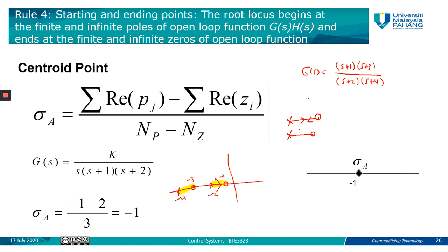So if you do not have an equal number of poles and zeros, that means I may have (s plus 2) over (s plus 3)(s plus 4). So I only have 1 zero and I have 2 poles. So how will the poles be aimed? That means they have to start from -3 and end at the one zero, and start at -4 and end where? I do not have another zero here. To which place should this pole go? That means we have finite and infinite zeros.